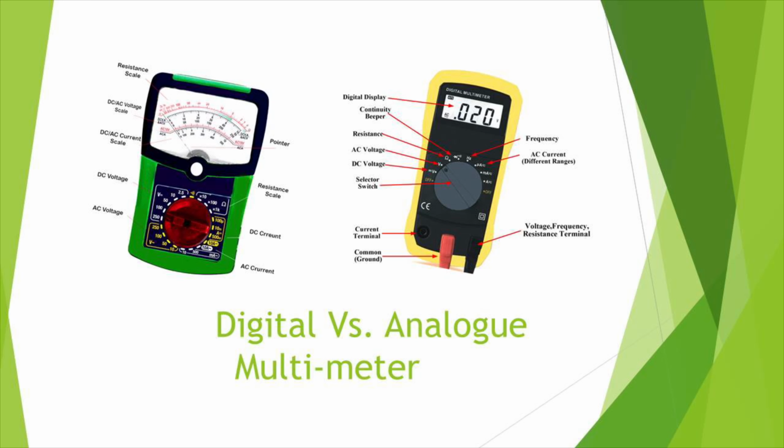This type of multimeter contains a moving coil meter and a selector switch, and can be passive or active. The analog multimeter has a screw to adjust the zero position. This needs to be done regularly in accordance with the user manual. The analog multimeter has a printed scale with a fine pointer. When reading the meter, your eye needs to be at right angles to the plane of the meter. Otherwise, you will get a parallax error.